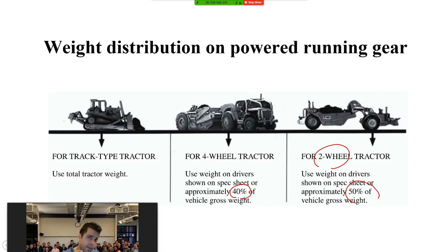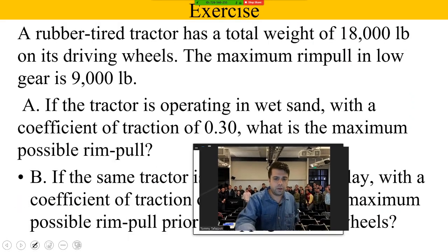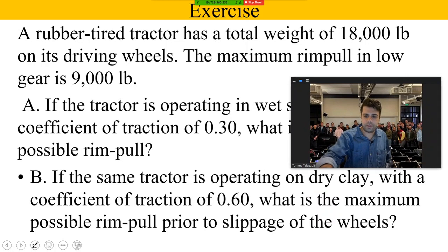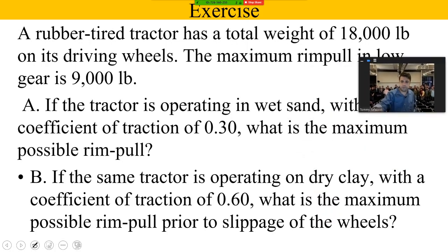First, you should look at the type of the machine, and based on that, decide whether you are using the total gross weight, if you're working with a tractor, or 40% or 50% of that weight.